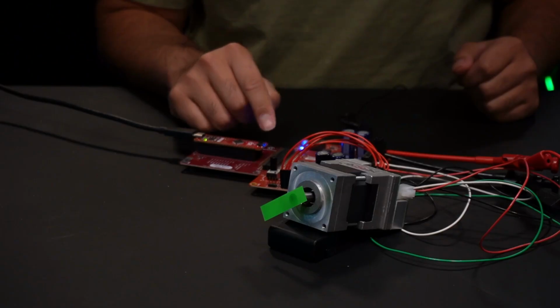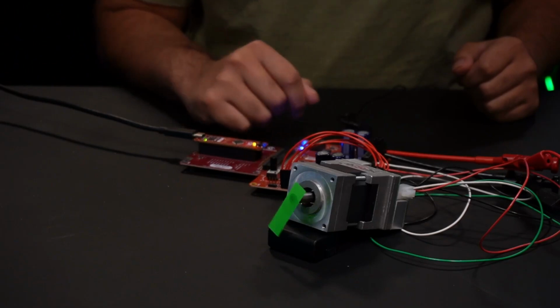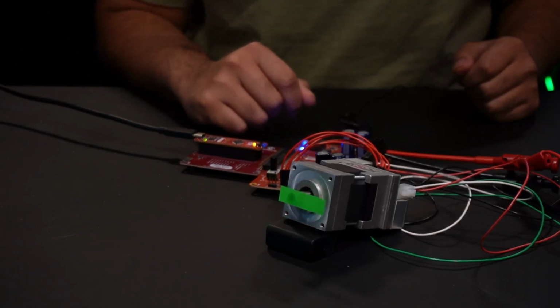Moreover, the waveform extension also has a feature called fault protection. In fault protection, the program can drive all the output pins into a predetermined state. A fault is triggered by either software or an event system on the microcontroller. Fault protection is useful when something isn't going as planned. For example, if we have a motor stalling, the program can drive all those output pins down to low.